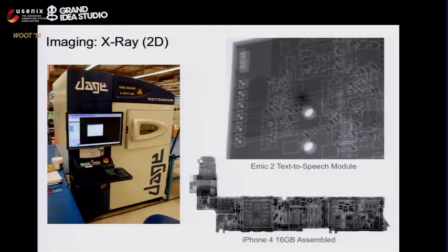So then on to imaging, some non-destructive methods, because most of these assume that you have no components on the board, which is okay if you have more than one to mess with, but sometimes you have assembled ones. Standard 2D X-ray, sort of an obvious type of thing, but not really that great. Usable for general purpose, simple boards. Here's a 4-layer board that I designed. I have some layer numbers up there, so you can get general information about a board using X-ray.